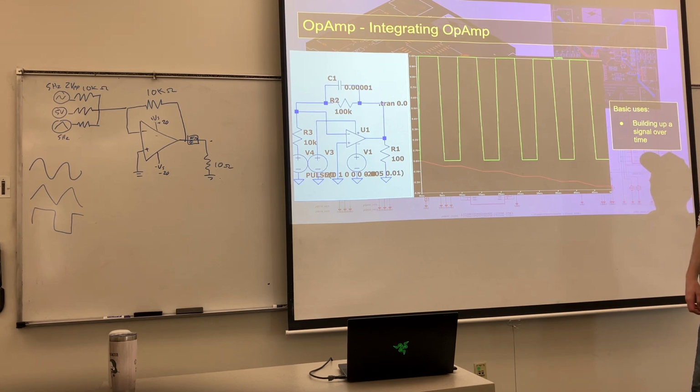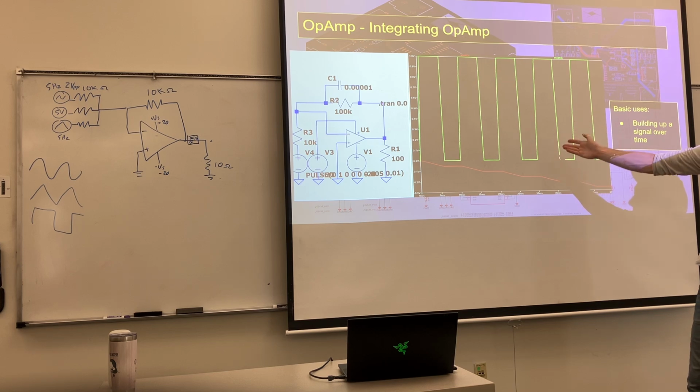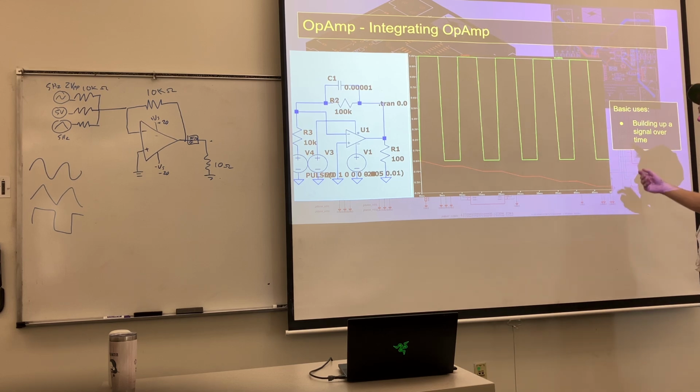And so if we have both of these in combination, we can use that for control systems. Basically, if you had a differentiating op-amp, you can use that to tell it not to go up so fast. Where if it has a high rate, it can say, I want to change from this point to this point slower. Which for dynamic operations is very important.